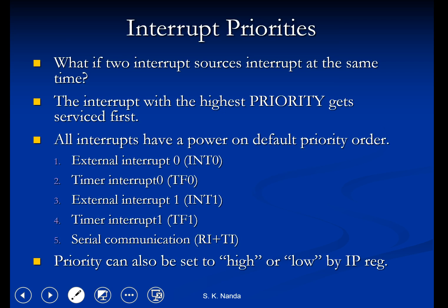Here we have interrupt priorities. Interrupt priorities upon reset may be used. As for 8051 interrupt priorities, the lowest priority interrupts are not served until the microcontroller is finished with the high priority ones. In case two or more interrupts arrive, the microcontroller queues them according to the priority. That is using the interrupt priority register.